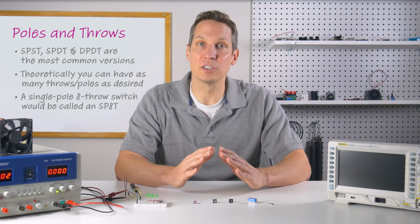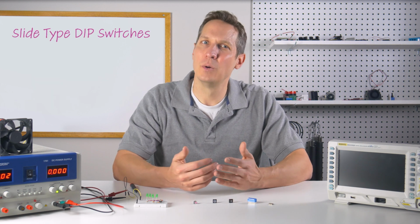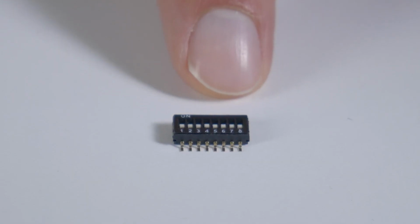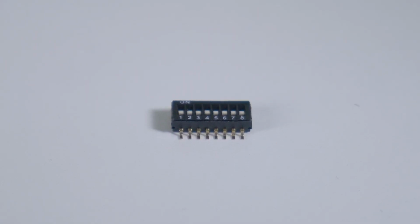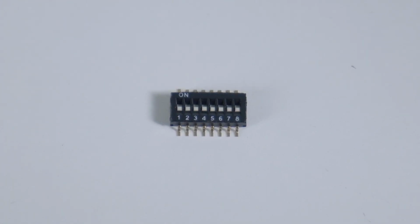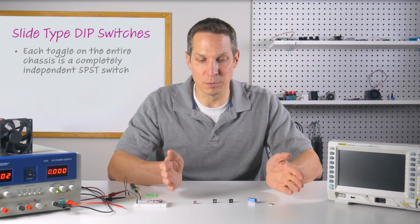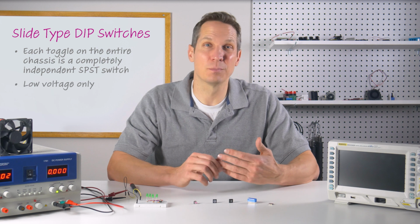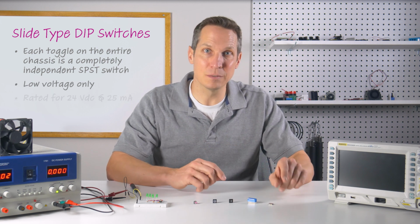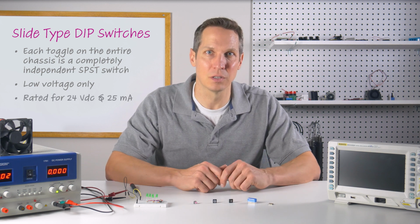Now that we've refreshed our understanding of throws and pulls, let's discuss the different types of DIP switches. When you think of DIP switches, you're probably thinking about the ones with slide actuators, like this one. The actuators can be moved either with a small screwdriver or your fingernail. With these, each toggle on the entire chassis is a completely independent SPST switch. At this size, and this is applicable to all of these, you can imagine they won't handle particularly high voltages or currents. While it varies between switches, this particular model is rated for 24 volts DC and 25 milliamps.